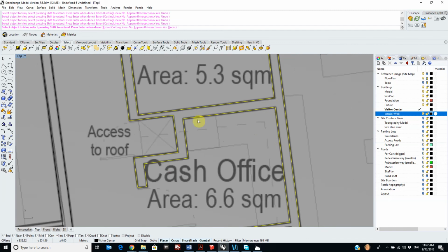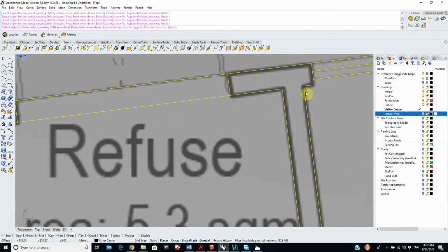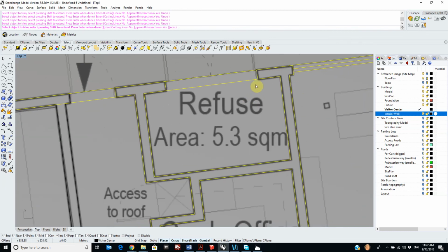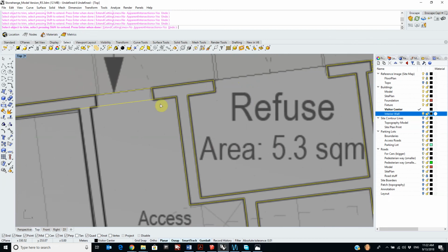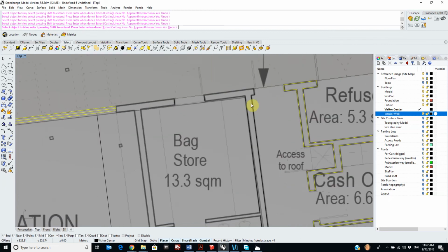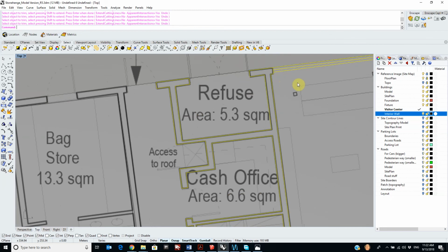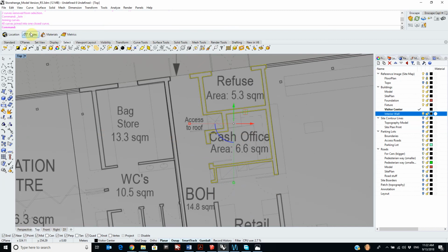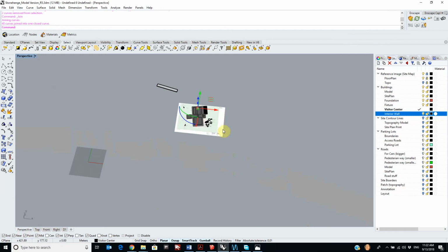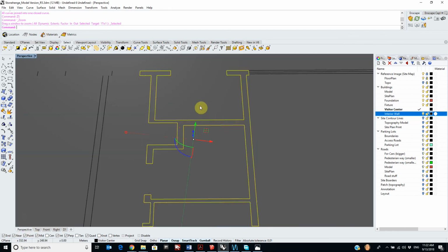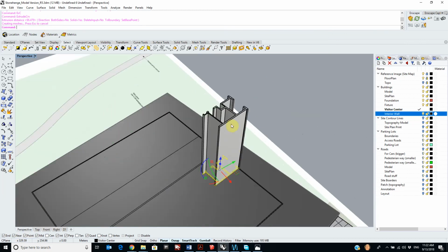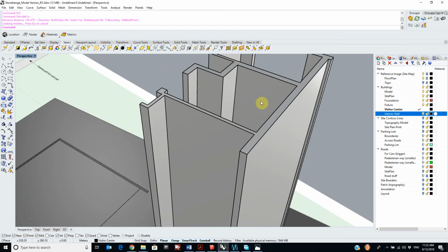To make it a solid wall, we need to trim it like this. Now I'm gonna actually get rid of these lines and draw it again, it doesn't matter. Okay, it was for the sake of the example. So if I click join now, I should have a closed curve. And you know what, why we did this? Let's zoom in. This is why we did this way, so we can extrude it later and make our walls out of it.